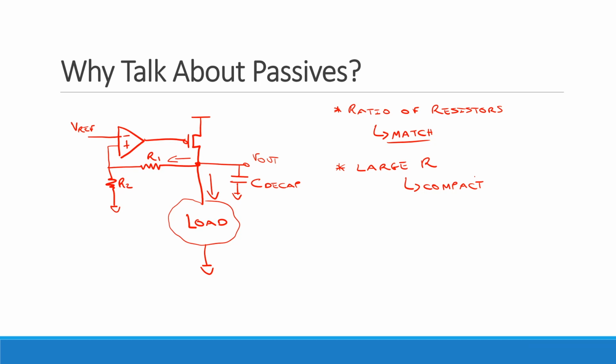Okay, great. That's actually several of the things that we've talked about. So that's almost all of them. Just to sort of clean off this example here, any other passive components that you think might be important in this context here? By the way, this is usually the first thing they tell you to look at when you do feedback loops. You want to make sure the darn thing's stable, right? So usually, not always, but usually, you probably want to put your dominant pole kind of over there, right?